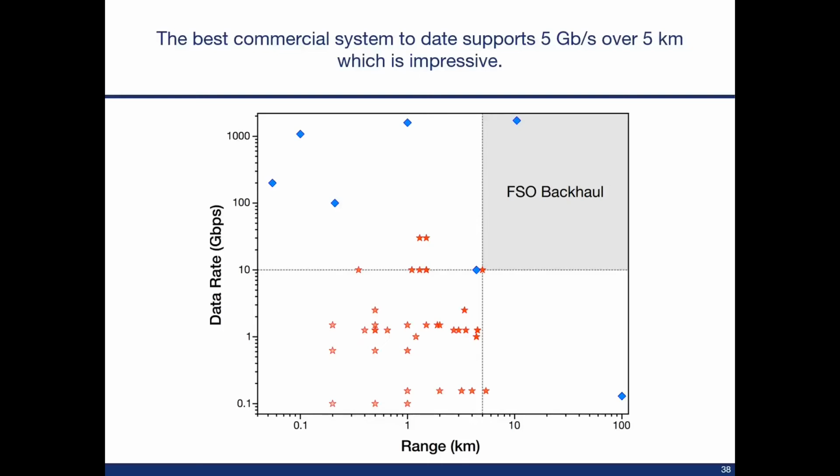It is important to remember that there is a specific link budget, and most systems will go further in clear weather. Weather isn't always clear though, and there isn't a standard way to report range. Some systems are more conservative and assume the worst case, where reliability is the primary concern. Other systems assume range is of primary importance, and so the reliability isn't necessarily 99.9% at long range.